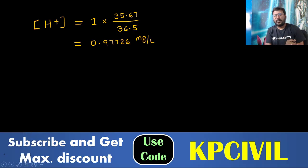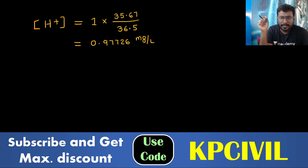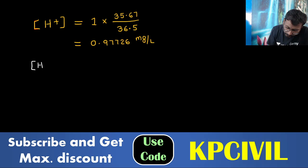But in the pH formula, in which unit do we need hydrogen? Mole per liter. That is very important. In the pH formula, hydrogen is always taken in mole per liter, so we need to convert hydrogen from milligram per liter to mole per liter.